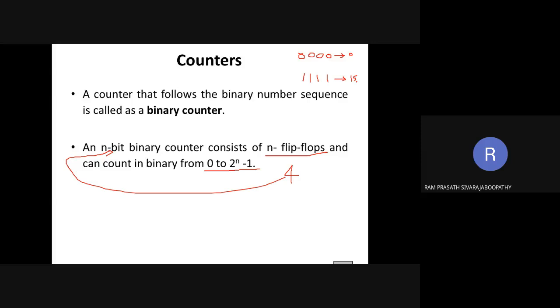I think Jeevita gave the correct answer. Rishwan gave the correct answer. Jayavardhini, Sabarish Shetty, it's not 10. Okay, we have 4 flip-flops. All flip-flops can be 0, 0, 0, 0 up to the maximum value 1, 1, 1, 1. So 0 to 15 is the correct answer. Okay.